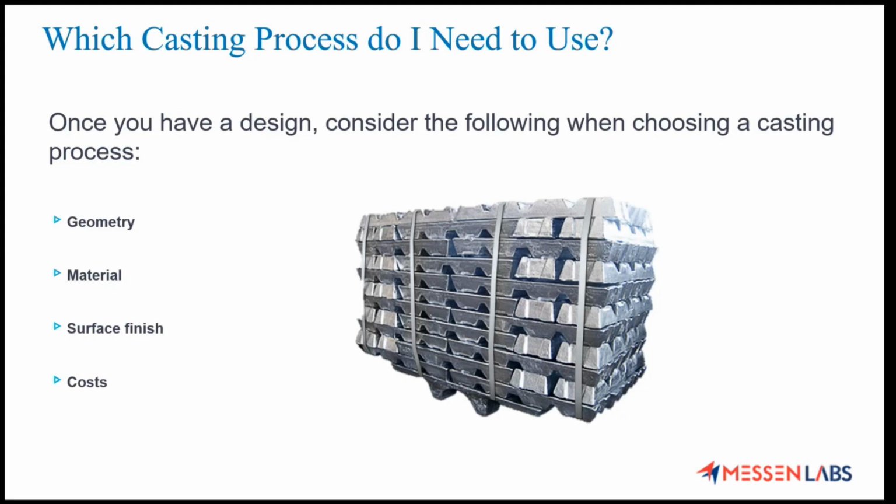Since we understood the different types of casting processes supported by Inspire Cast, now we will be in a dilemma on which casting process needs to be used. The casting process can be chosen by 4 different variables. The first one is the geometry, then material used, surface finish and cost. So let's go through the variables one by one.